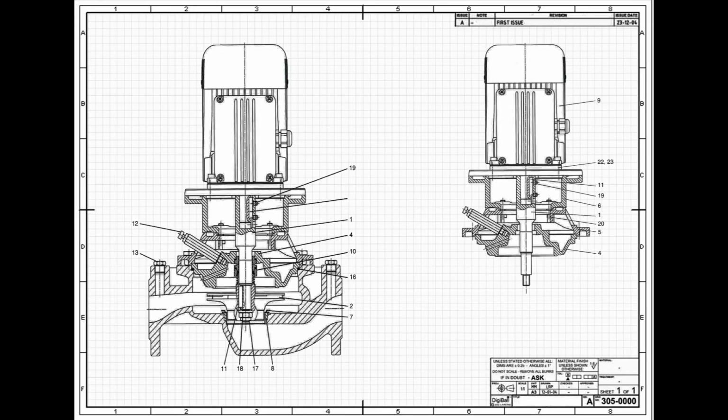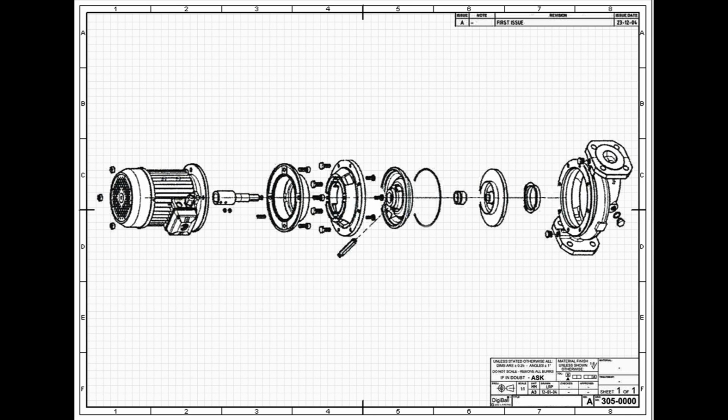A centrifugal pump is one that moves liquids through pipelines from a collection tank or vessel to another. It does this by supplying energy to the liquid through a spinning impeller, building up the pressure in the liquid and giving it enough speed to flow through the pipe from one place to another. These pumps can also be used to move slurries of liquid containing solid matter, like sand, powders, and even some foods. They are used for this main purpose in industry.